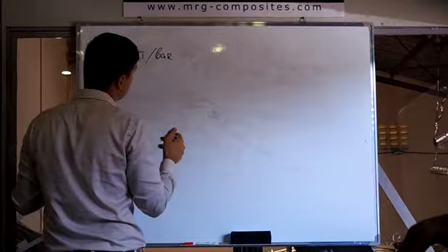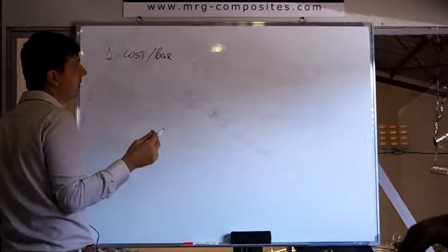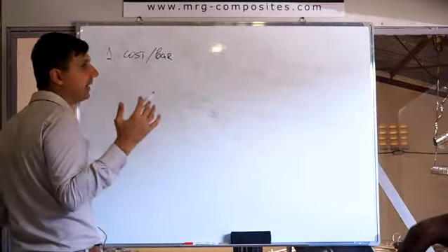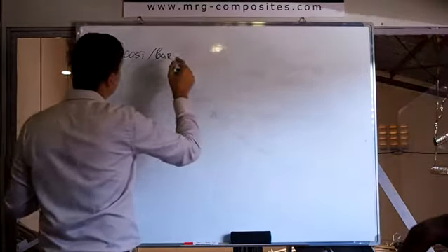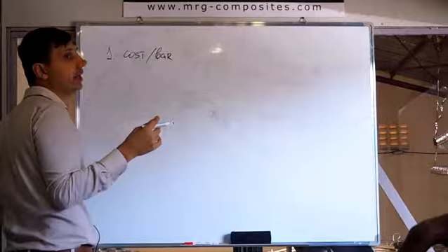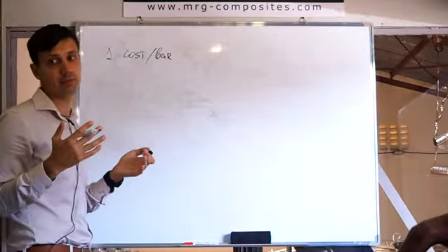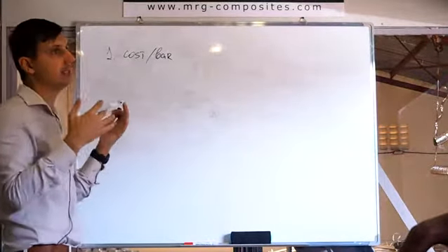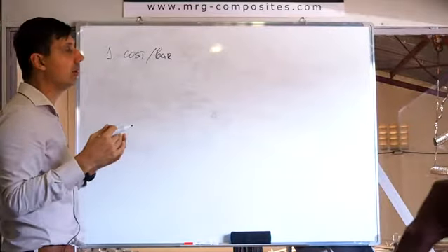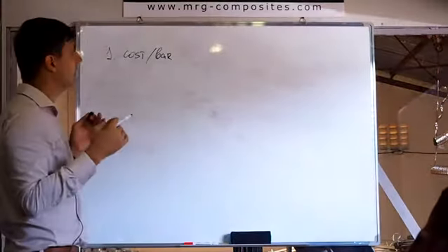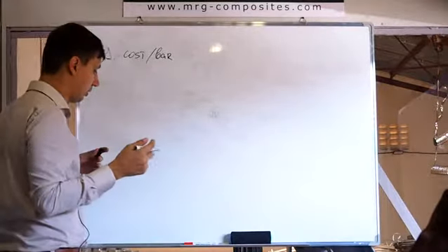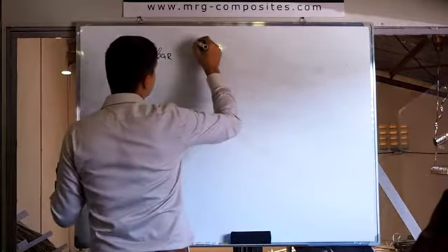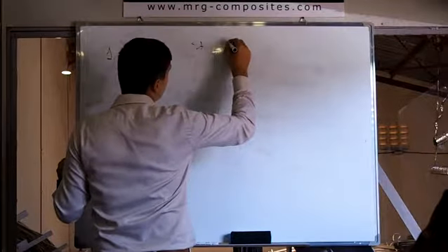Another thing, here I want to stop one more time on this idea: if you want to compare cost, you can't compare Y12 and FRP-12, or Y16 and FRP-16. You compare only bar according to the table of substitution. So let's say if you need steel, this is FRP.